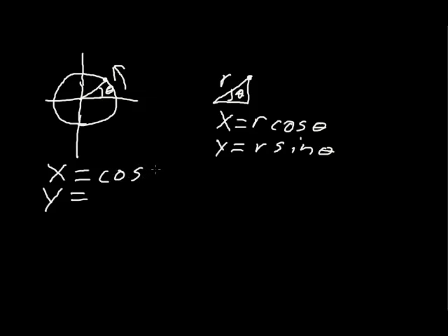And I'm going to switch theta to t, since that's what we'll be using in SolidWorks. Since SolidWorks asks for the limits on t, we're going to have to figure that out, and that's of course going to be a full revolution, which is 360 degrees, or in our case, we're going to be using radians. So t1 is going to be 0, where t1 is the start, of course, and t2 is going to be 2 pi, because there are 2 pi radians in a circle.